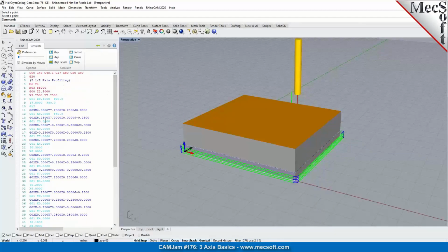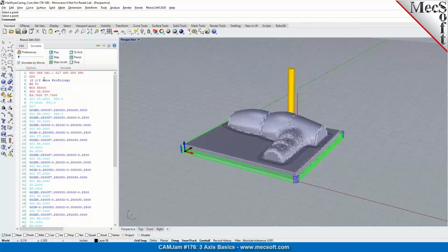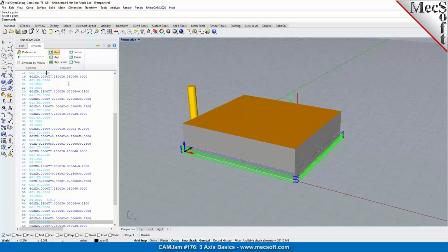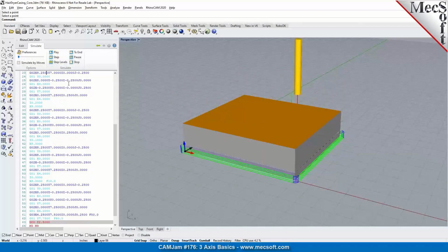In the editor, the code is automatically color-coded based on the motion type: rapids, linear, arc motion. You can make edits to the G-code. You can also go back and rerun the simulation. What you're seeing is the simulation of the G-code file. It's nothing to do with the internal toolpath, so you're basically verifying whether your G-code is correct or not. That's precisely why we wrote this product, and we make it available to all AMS customers of Standard and above.